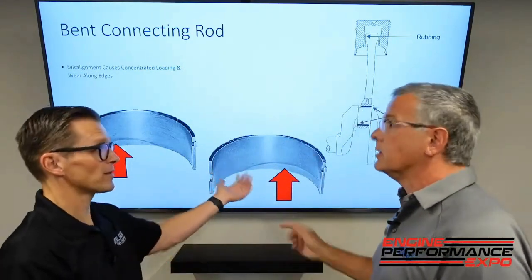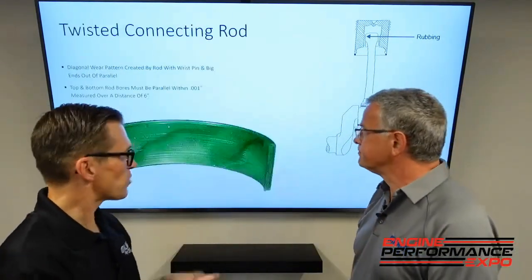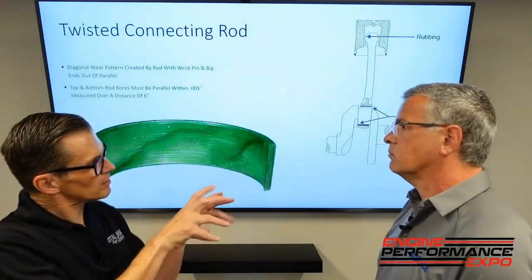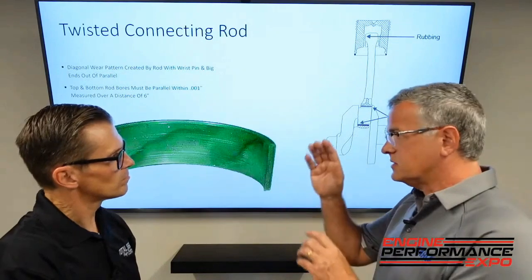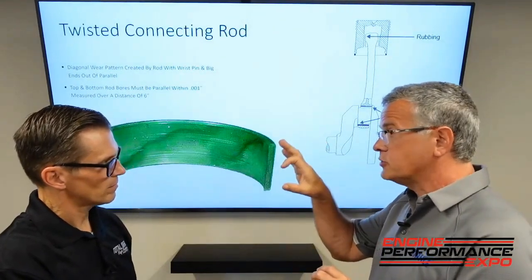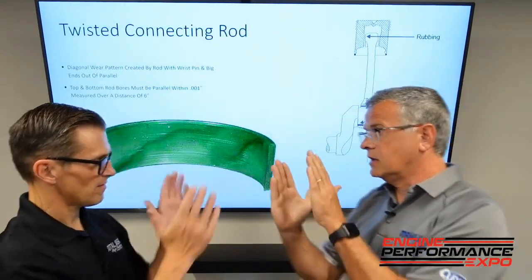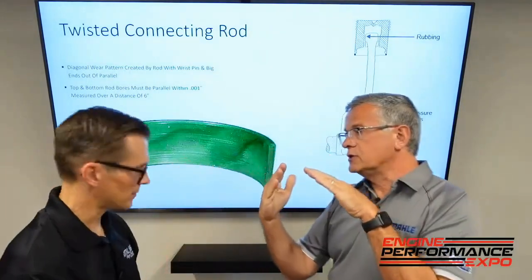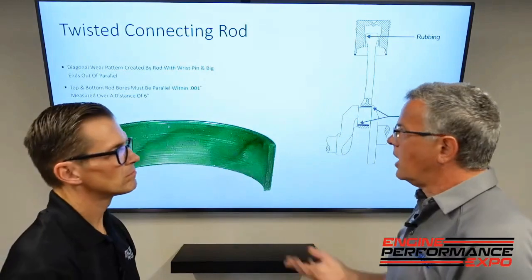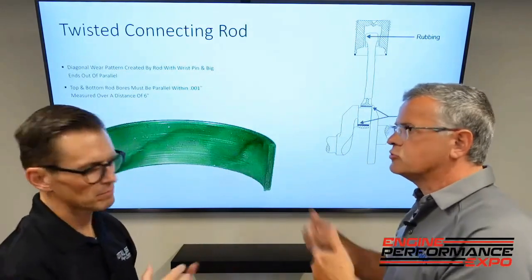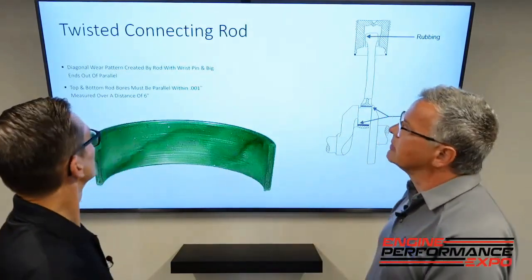Mains, and this will show up on the rods. That is correct. Can you ever see any crankshaft flex show up on the connecting rods? No, typically the crankshaft flex is from the rod journal to the main journal, and it's flexing this way. So that stays pretty well round. Now there is some ovality that happens in high RPMs, high frequencies where it's drilled too much, but we're not going to go there.